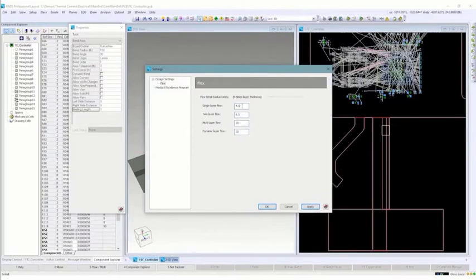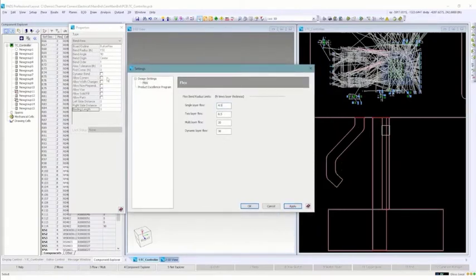There are specifications generalized in the industry for how much you can bend the flex material based on the number of layers or how thick it is, to make it reliable. And if you're doing things like dynamic bending, say like a cell phone or a computer, or anything where the flex is going to be moving all the time, or a mechanical device where the arm's moving around and has a flex on it, the bend radius has to be much larger so that the copper doesn't break. And the tool dynamically is going to verify this. I'll show you that here in a second.